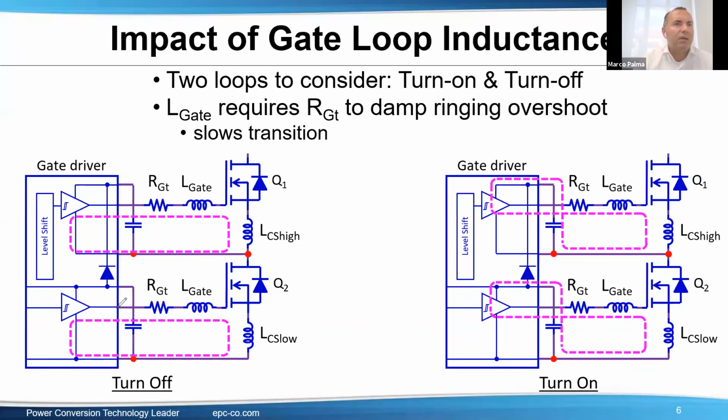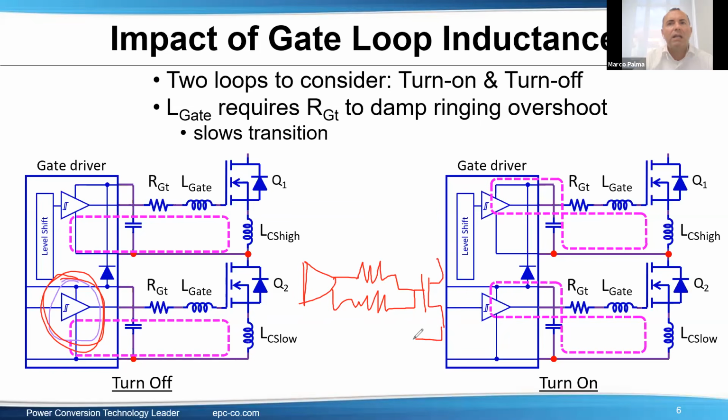And here you see in reality a GaN FET gate driver. If you consider this part, let me change color so you can see, let's design it here. It has two outputs, one to switch on and the other one to switch off, and they go to the gate of the GaN FET. The reason why you have two outputs is that you have a pull-up MOSFET inside the gate driver and a pull-down MOSFET. That means this resistor here is definitely smaller than this one.